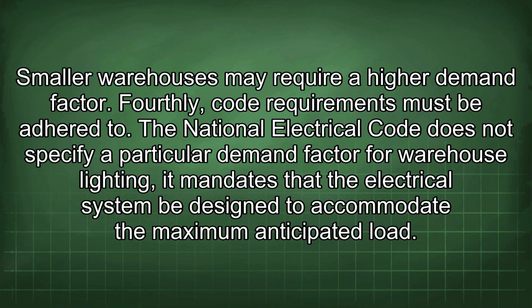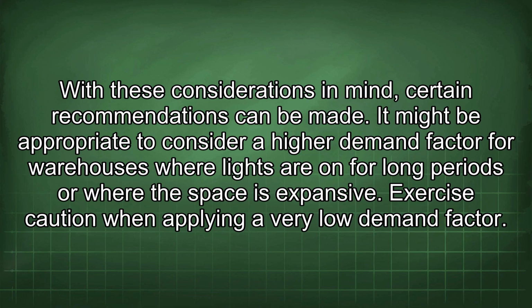Fourthly, code requirements must be adhered to. The National Electrical Code does not specify a particular demand factor for warehouse lighting. It mandates that the electrical system be designed to accommodate the maximum anticipated load. With these considerations in mind, certain recommendations can be made. It might be appropriate to consider a high demand factor for warehouses where lights are on for long periods or where the space is expansive.